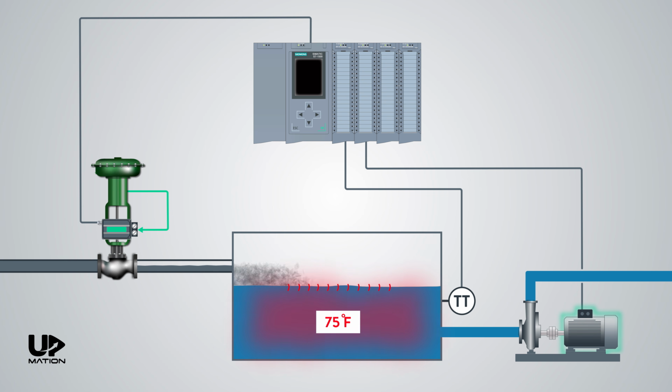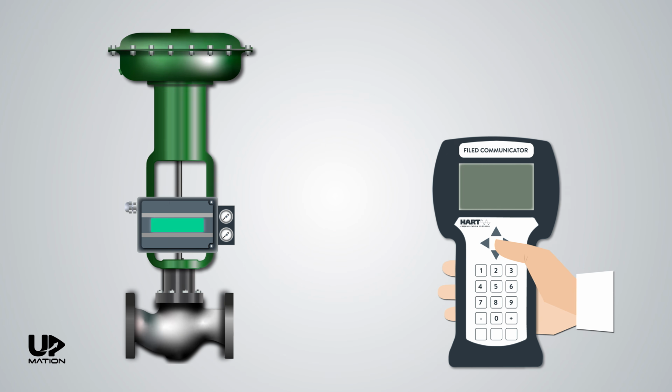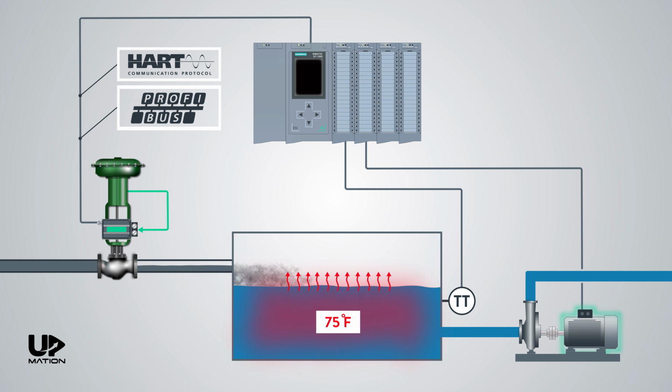Using digital positioners, we are able to communicate with the valve by different types of protocols, such as HART or fieldbus protocols like Profibus. By such digital communications, we can calibrate control valves way more easily using handheld communicators without tackling time-consuming and sometimes difficult mechanical adjustments. Besides, we can send some feedback from the control valve to the PLC or DCS via these communication protocols.